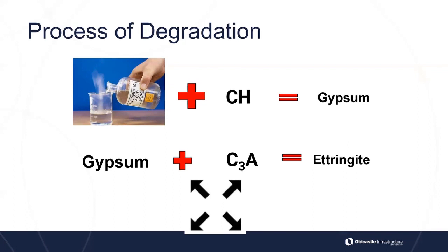So think about what would happen to hardened concrete if you get ettringite in the pores or into the little cracks of the concrete, and it gets hydrated and now it starts expanding. This expansion can cause concrete to crack, to spall. It causes aggregates to pull away. It allows for deeper penetration of the acid, and then it continues this corrosion cycle further and further.